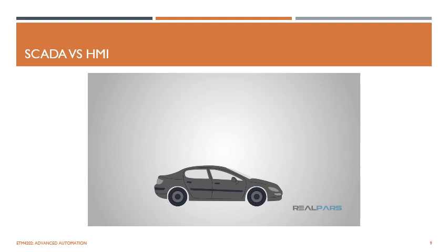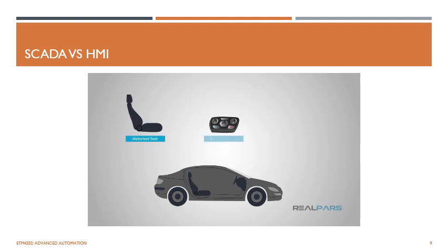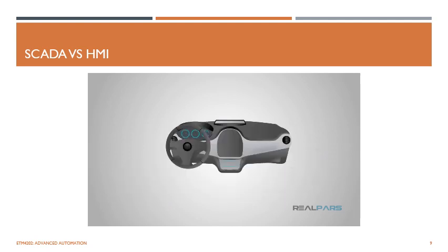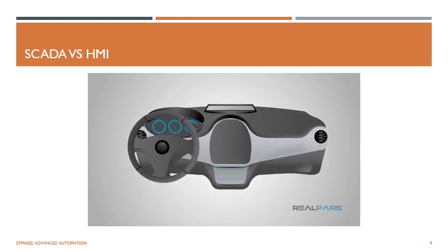I like to think of a SCADA system kind of like a modern vehicle. You have several different sensors connected to different computers on board. Most of your interior features like motorized seats, climate control, and other things are controlled by a BCM, or Body Control Module. Most of your engine functions and sensors are monitored and controlled by your ECM, or Engine Control Module. These modules all send information to a main screen in your dash for you to see and control through driver controls, which is essentially your HMI.